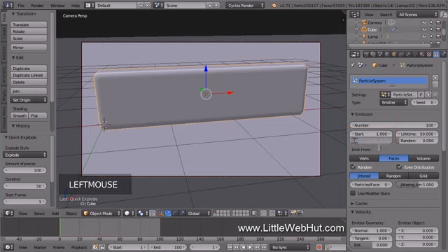Set the end value to frame 70 and the start value to frame 20. The end value needs to be larger than the start value, so set it first. The lifetime value controls how long the particles are displayed. Set this value to 100 so that the particles will stay visible throughout the entire animation.